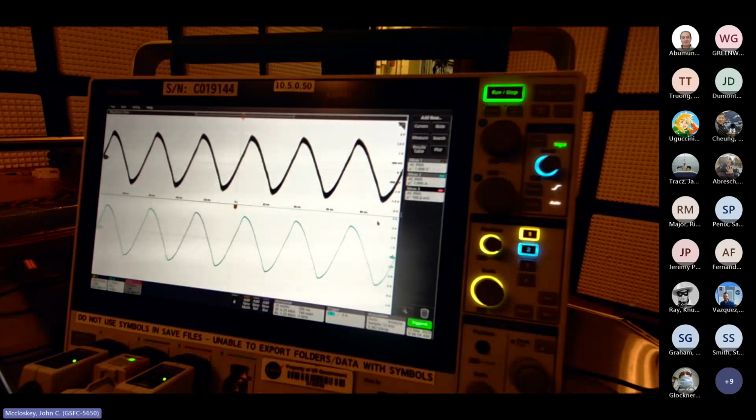The current is 1.996. Okay, so if it's 1 volt across half an ohm, we would expect 2 amps. That's essentially what we're getting, just shy of that, but about 2 amps. So that's what we would expect. Okay, and that's pretty much it for that frequency step.